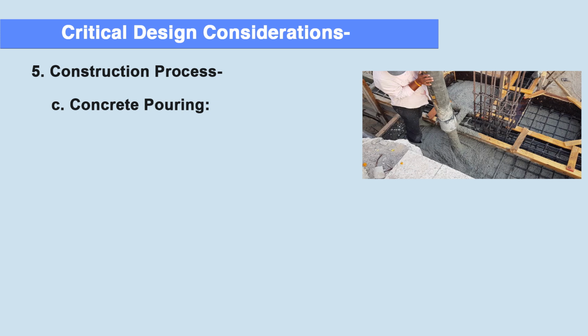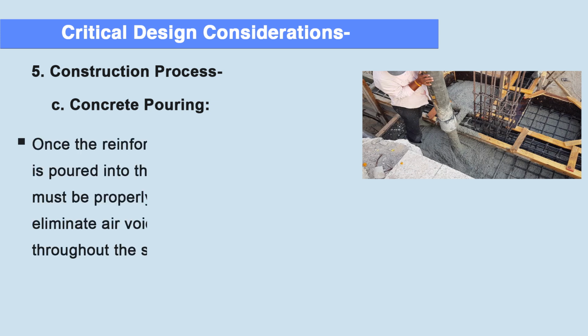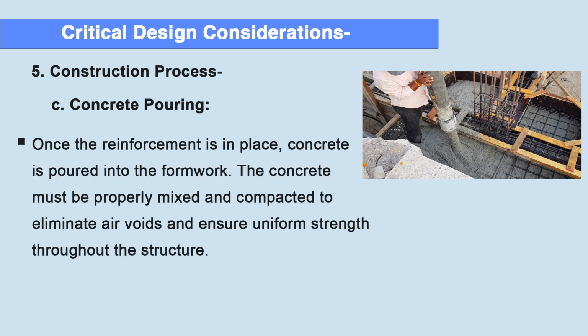Then the next step is concrete pouring. Once the reinforcement is in place, concrete is poured into the formwork. The concrete must be properly mixed and compacted to eliminate air voids and ensure uniform strength throughout the structure.